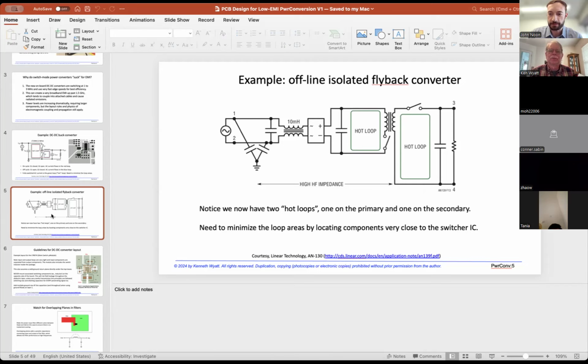So most of my techniques are bench level. If you take a look at the articles that I write, it's all tests and characterizations that you can do right on the workbench to predict performance. A couple of my articles were on pre-compliance testing, for example, where you can set up your own pre-compliance test for radiated emissions, and some of the cautions.